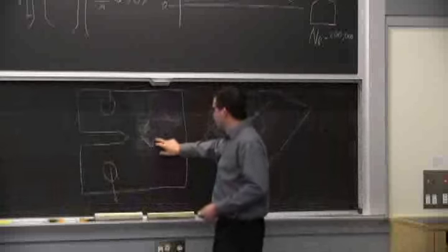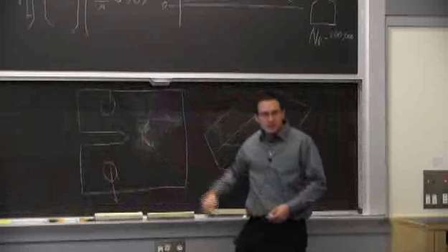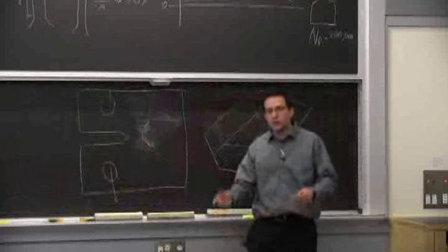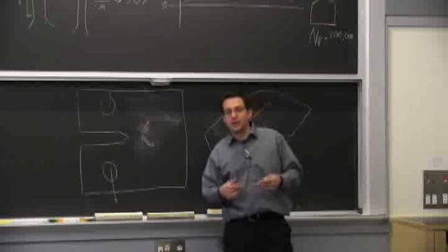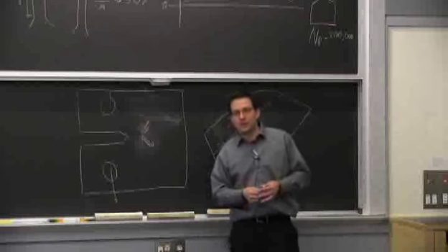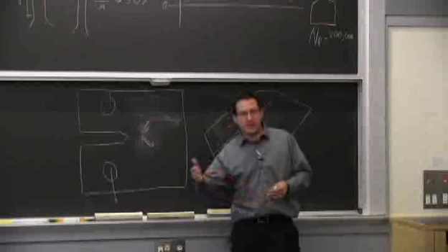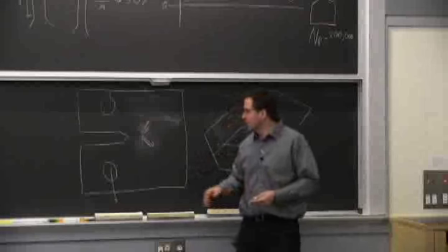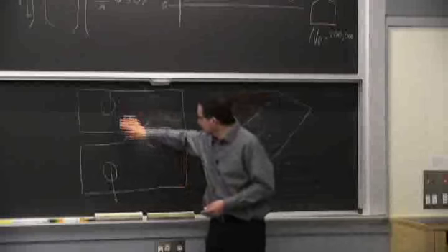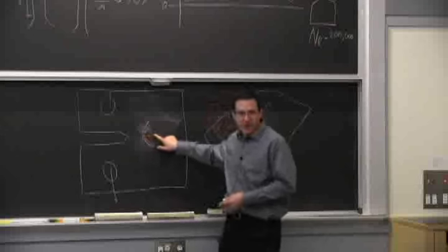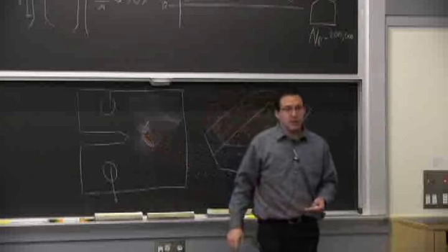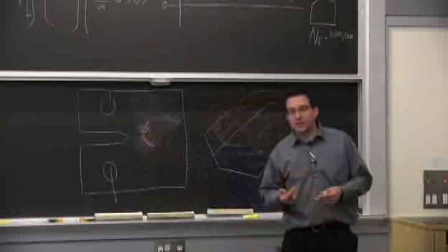When we're doing this, we can really keep track of where the crack is. We don't have to go back after the fact on the microscope and say, oh, it was here at that point in time. So as we do the test, and even from just the compliance of the sample, which changes with crack length a lot, we figure out that curve.